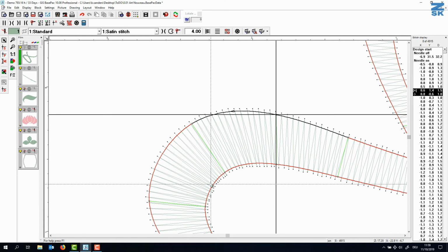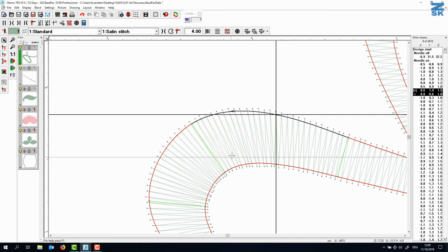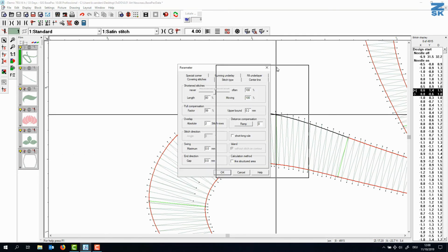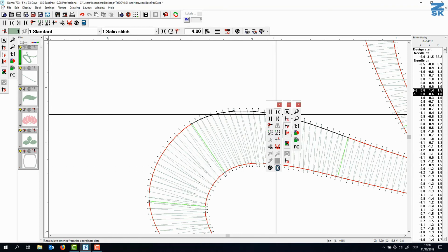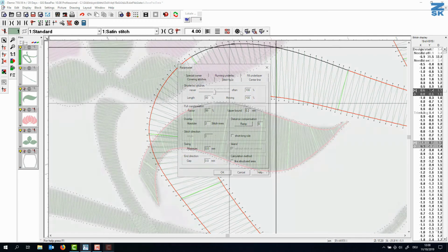If you then consider a straight corner of a letter or something, you always end up with a hole in your material, especially if you work on piqué fabric. So what we do, we have our stitch shortening and say we do it 100%. That means, yes, whenever necessary, do it. If I say often, it's actually more. So the standard value is always set up on default. Just keep it in the back of your head if you need it one day.